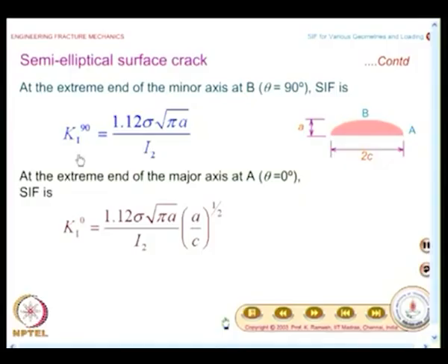The crack can have a preferred way of extension. We saw in the case of an elliptical flaw, the elliptical flaw which is embedded would try to become a circular flaw, because that is how the stress intensity factors were varying. So, yes, similar thing also can happen in the case of a surface flaw, and this also helps to appreciate the concept of leak before fracture. You have stress intensity factor higher at this point, so the crack will try to penetrate inside rather than on sideways.